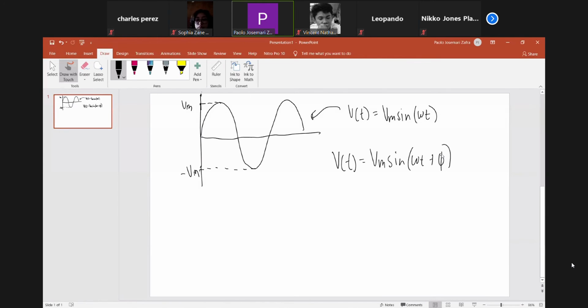So when we say frequency domain, we are simply changing our sinusoids or sinusoidally varying functions into complex numbers. And upon doing that, for instance, we would like to obtain the phasor of your V of t. So it's usually represented by a capital letter, sometimes with an arrowhead above the letter. So you simply take the amplitude as well as the angle. Okay, so that's basically it.